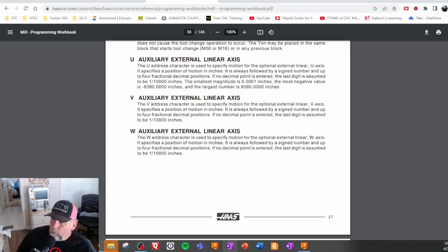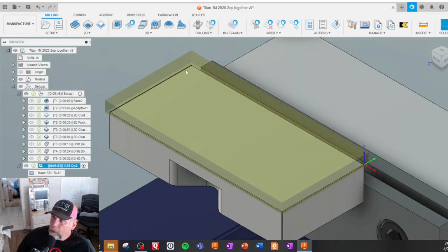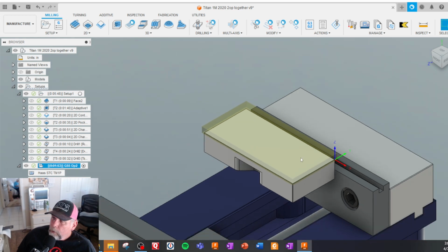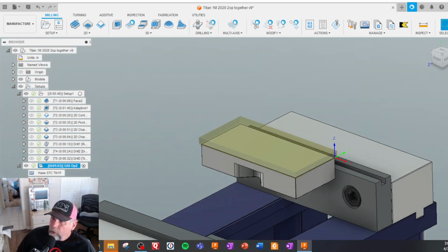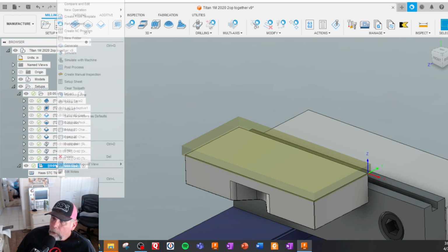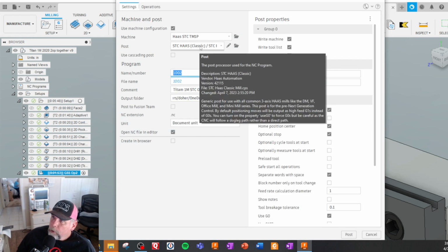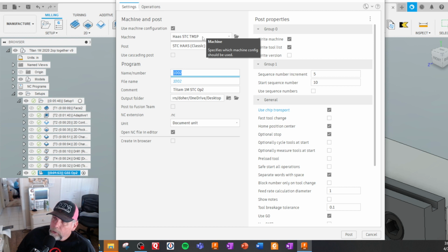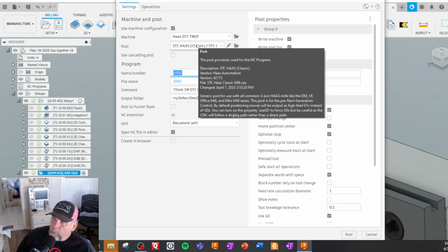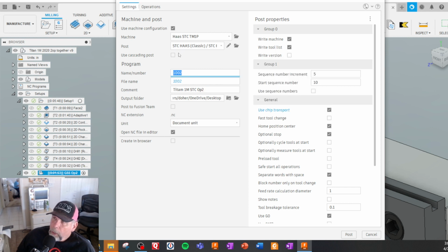All right, back to our G code Fusion thingy here. We got face mill. We're gonna rough and chamfer, right? I'm going to do a couple different ways. I'm going to do post process now. I have my post selected, but I also have a machine selection. This is not a machine for simulation. This is just a machine with some basic parameters in there. But it actually automatically points to the post. That's one plus. Another thing I found out, if you program in the 10,000 RPM range, and if you go use a machine in the 6,000 RPM range, it'll give you a warning.